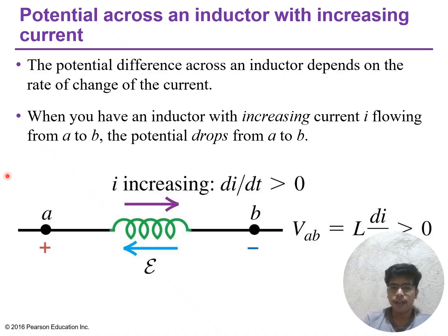If current flows from A to B, then V subscript A is less than V subscript B, opposite to a resistor, where V subscript A is greater than V subscript B. A larger inductance L or faster change in di over dt produces a larger opposing voltage. This voltage represents energy being stored in the inductor's magnetic field.